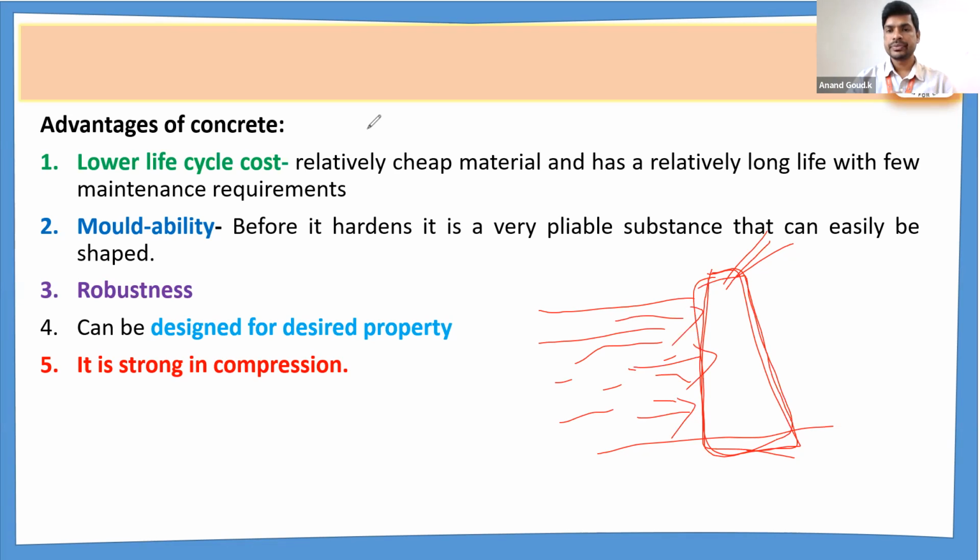If you take metal, you can construct this retaining wall with metal also. But what happens if you use that metal in water-logging areas? It is going to get some corrosion, and it is going to fail. But what is this concrete structure going to do? It is going to resist the huge force coming from the water, and the water absorption is also very, very less. It cannot degrade that much.